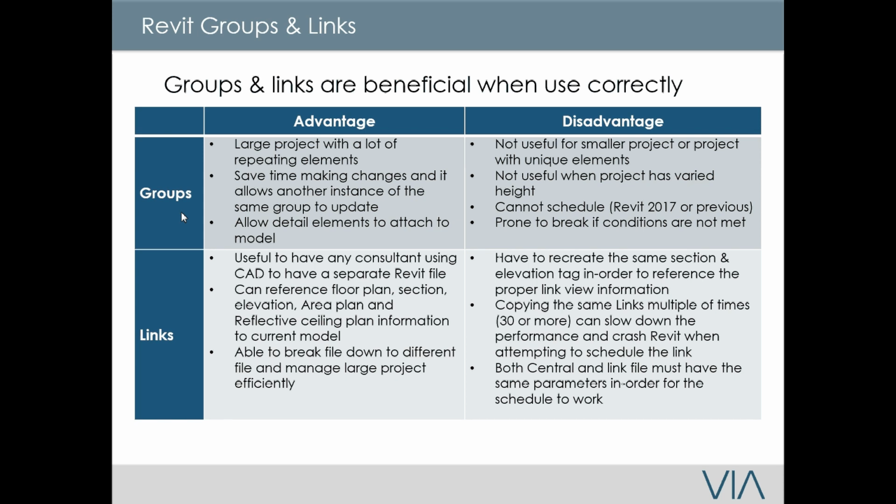The reason why I would do this is that you want to keep their model as clean as possible, so that it would not infect all the line types, all the errors from AutoCAD. You just want to create it as a separate file. Also, links have the advantage that if you have a very complicated level-to-level height, where you have to change, let's say the site is sloping, or you have a lot of variations in height, links do actually help you, okay?